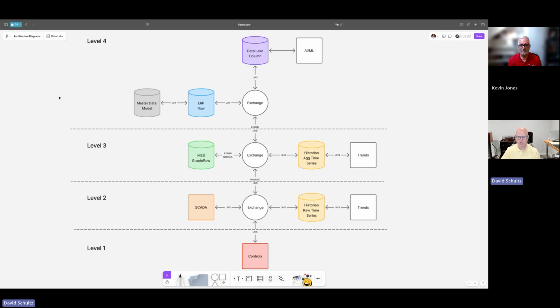So at this point, Sparkplug, since you mentioned it, or I guess I brought it up, is really more of this level one, level two. This is where you're going to use Sparkplug. At this point, you're going to start creating these large JSON structures that are then going to be ingested by the data lake itself. Yes. So what I'm getting at is UNS is telemetry, it's time series, it's contextualized. It's not just your process historian data, but yes, the structure of that information is going to follow that unified namespace concept, where your topic structure is going to follow that ISA 95 hierarchy or equipment hierarchy model.